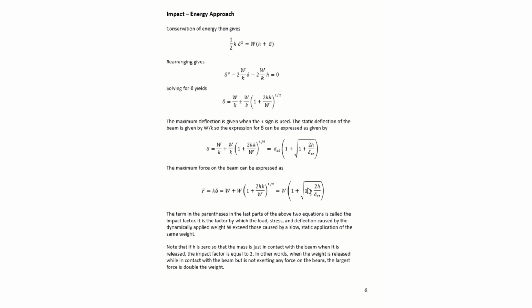It's the factor by which the force is increased due to the impact, the force caused by the dynamic excitation versus the statically applied load. And here again, note that if h is equal to 0, then we get the factor of 2.